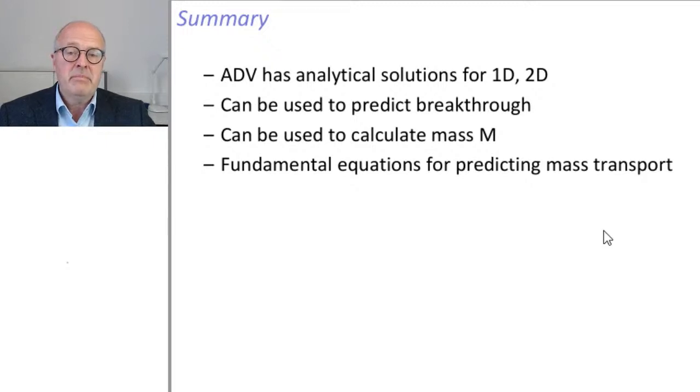But I can measure very well 0.2 microgram per liter. I'm a factor of more than 10 below the visibility, and I still have a factor of 100 above the detection limit. So the perfect target concentration would be 0.2 microgram per liter or 0.2 milligram per cubic meter.